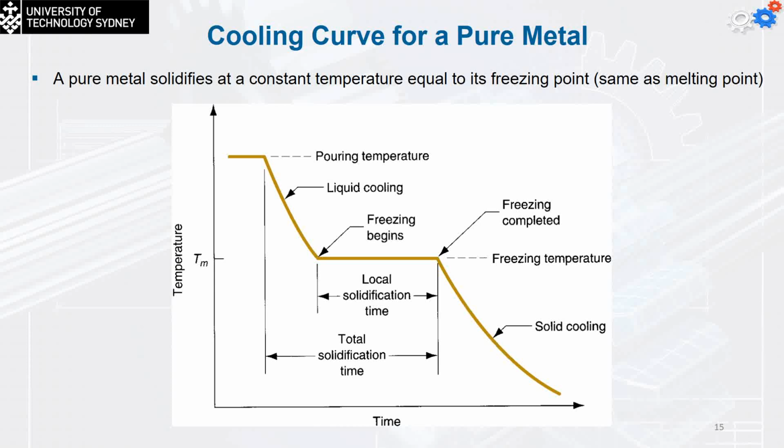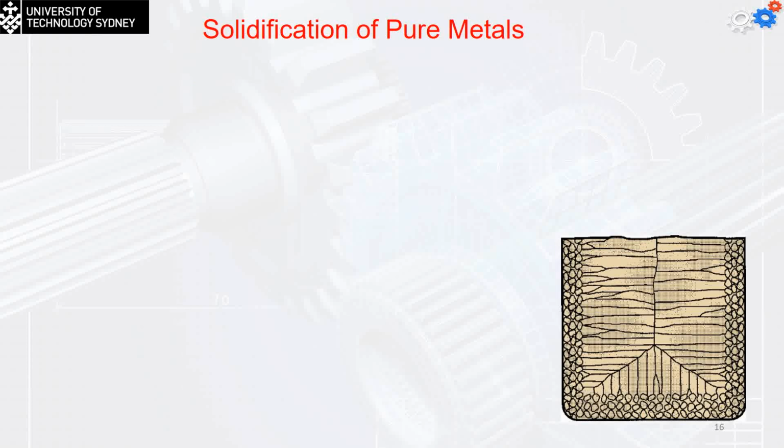Because of this process, when I start to pour the metal, whatever temperature I have for the mold is going to be too cold compared to the molten temperature. Let's say the mold is at 70 degrees or even 100 degrees, but the molten metal is at 1,500, for example. That means we have 1,400 delta T. So we are going to have chilling at the wall. The chill is too cold compared to the metal, so you can see that it will be chilled very fast.